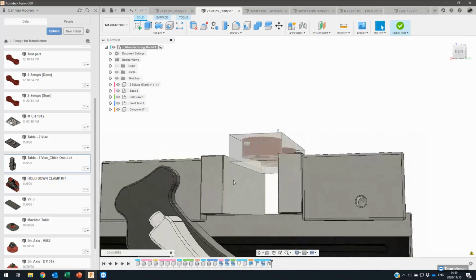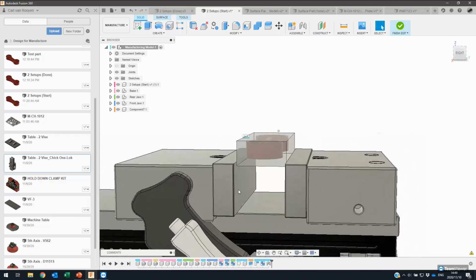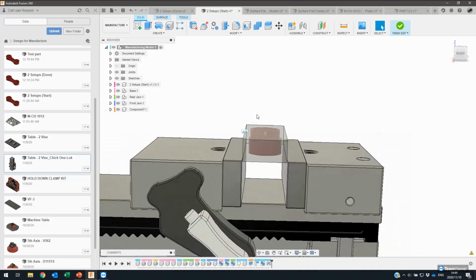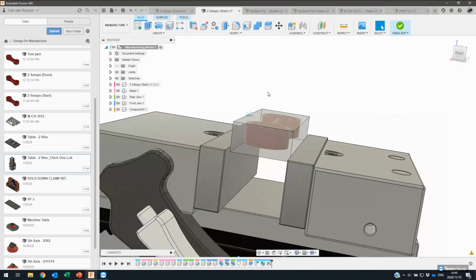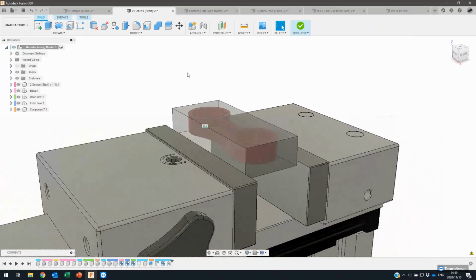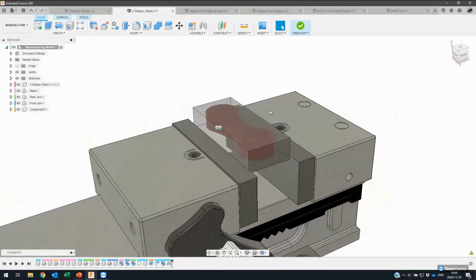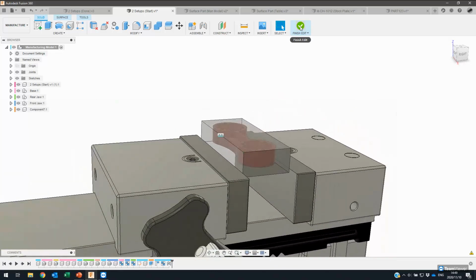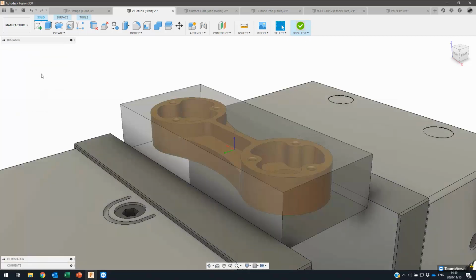And so that now puts the stock in the vice. If I really wanted to, I could put parallels in there so I know the exact dimensions. I can still move this vice as required, move that joint to position it, but I'm going to leave it there for now. So that would be my first manufacturing model that represents the component, the fixture, the stock.